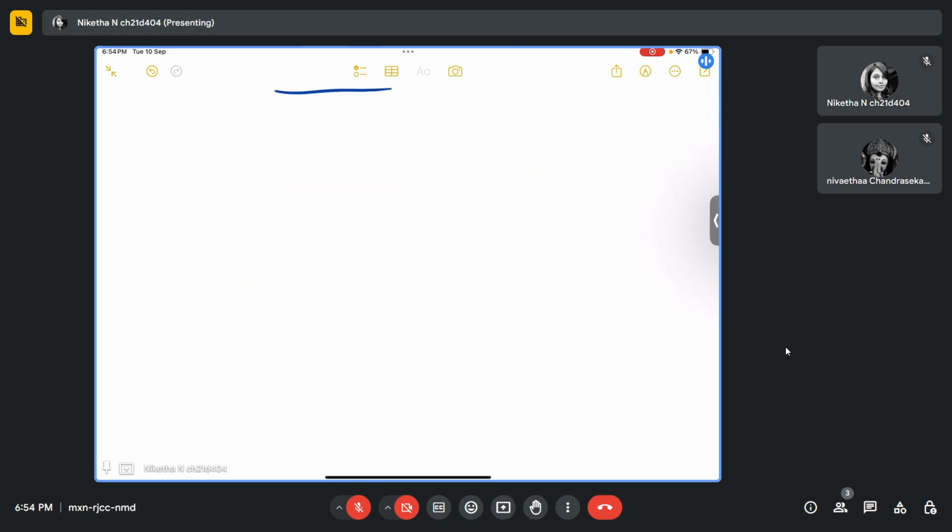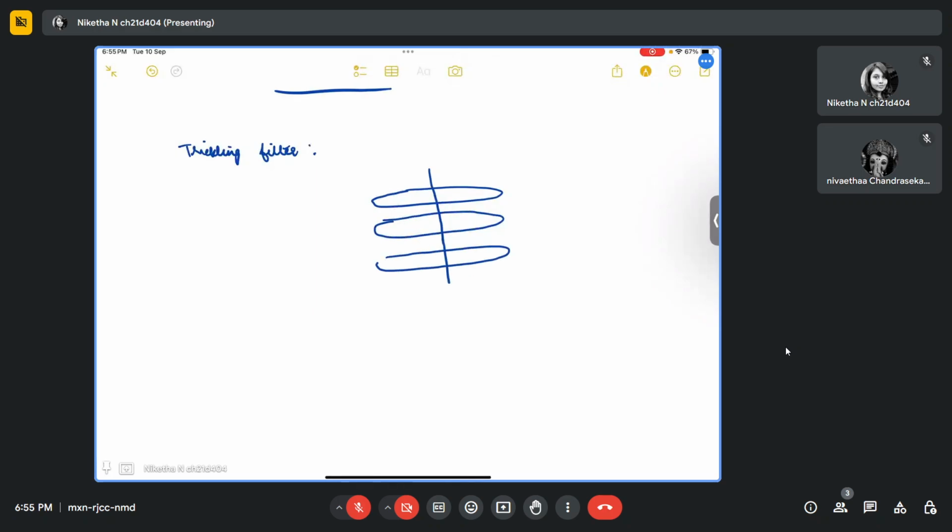Okay. So now we have seen ASP. Then we will come to trickling filter. So this is the second most commonly used aerobic process after ASP. What happens here is you will have a filter like apparatus. On this we will have various particles, okay? Like maybe Raschig ring.